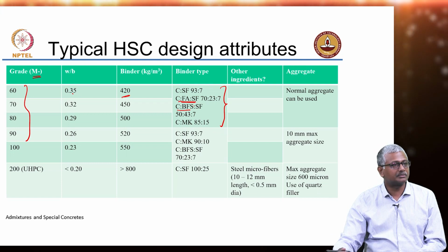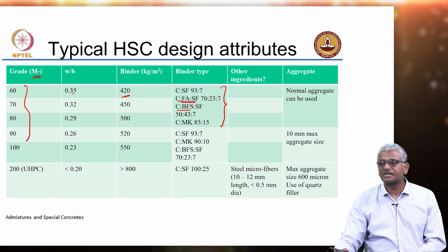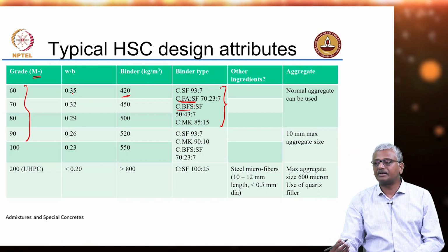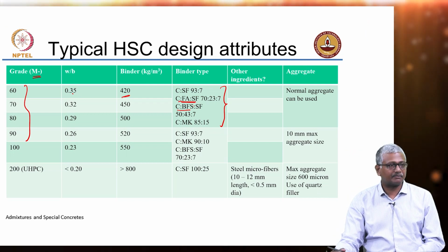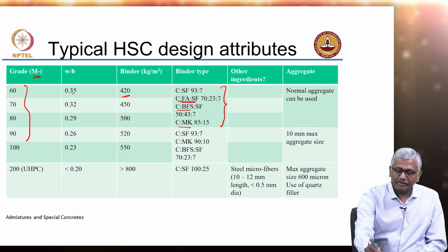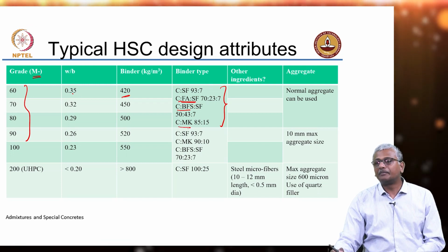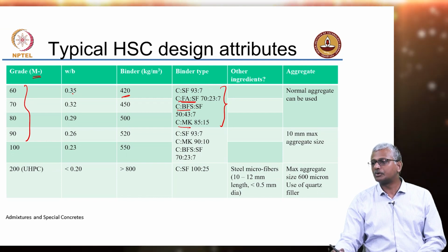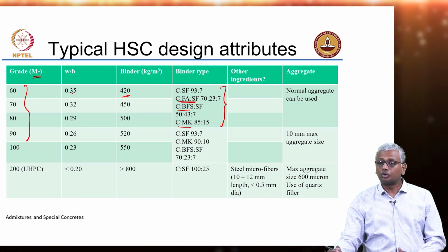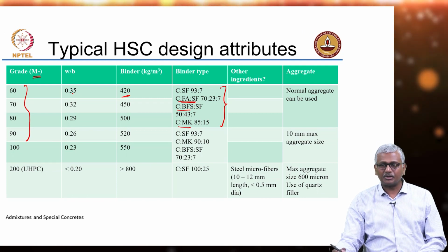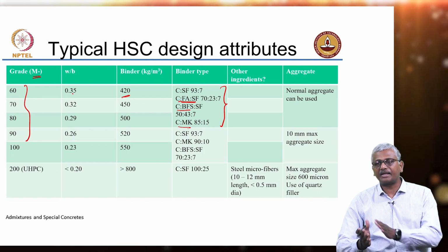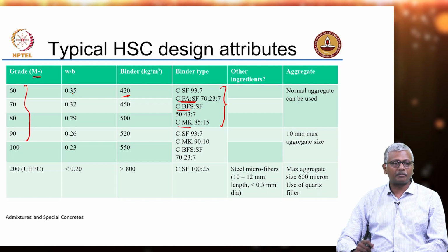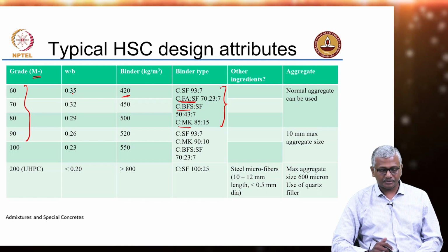because you are maximizing the slag content because of its latent hydraulic properties and the fact that in most cases slag is available much finer than cement and is able to contribute to early age strength development also. Cement metakaolin combinations could also be used. Metakaolin gives a slightly higher fraction of usage as compared to silica fume. You can go up to 15% without too much of a loss of workability, but you need to still be aware that because of the clay structure, your superplasticizer effectiveness can reduce if you do not do a proper assessment of the compatibility issues.